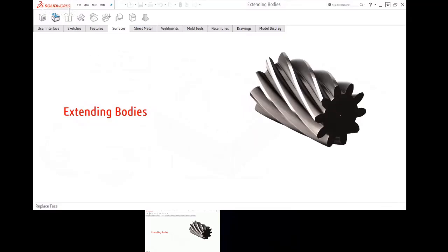Traditional solution. Convert entities on the face. Yep. Okay, so convert entities on the face gives me the shape, and then I need to know what the helical pitch is, the length, and I would just create another sweep on top of the existing sweep. And hope, yeah, probably a guide curve, because that profile is going to get pretty twisty, probably. Doable, and you hope you get it right.